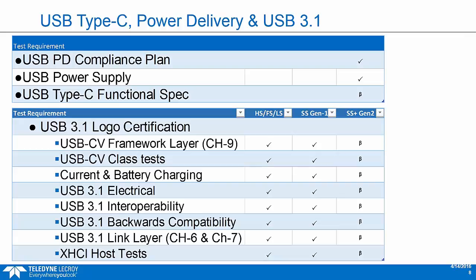Now, if your device also has USB functionality, it has to pass all the relevant USB compliance tests. So they've been certifying Gen 1 SuperSpeed for a long time. For Gen 2, the 10 gig devices, they're still considered beta or dry run at this stage, but they should have all the tests in, all the fixtures they need to start testing 10 gig, later this year.